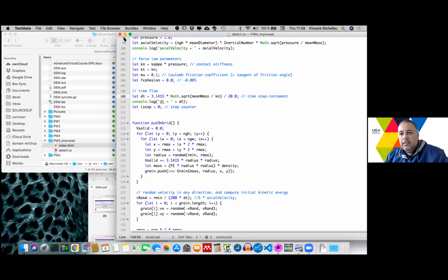Generally, KT over Kn or Kn over KT controls the Poisson ratio, only in the elastic domain. Okay, so this is the way KT should be set. So if we care about elasticity, KT over Kn or its inverse controls the Poisson ratio. Most of the time we choose KT equals Kn, but still this is a recipe.